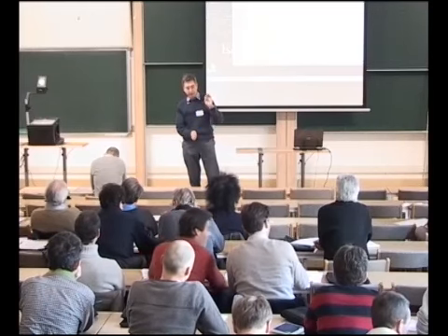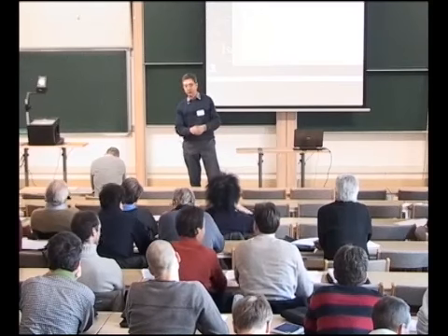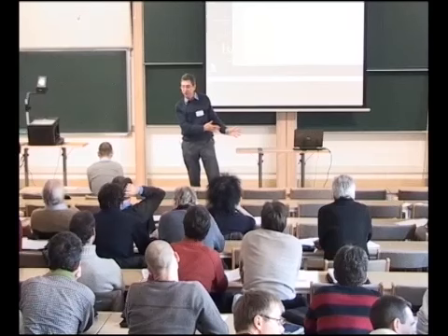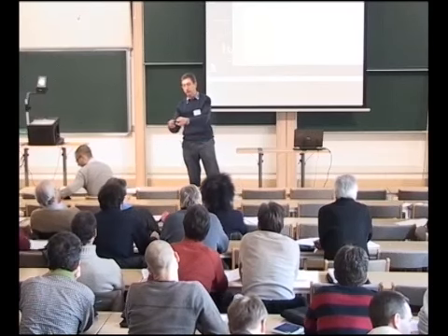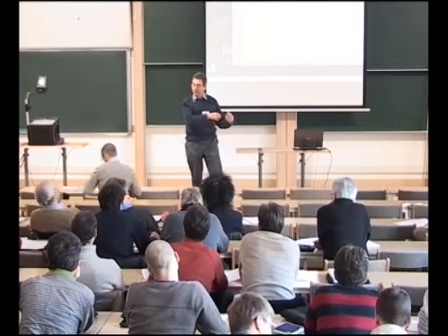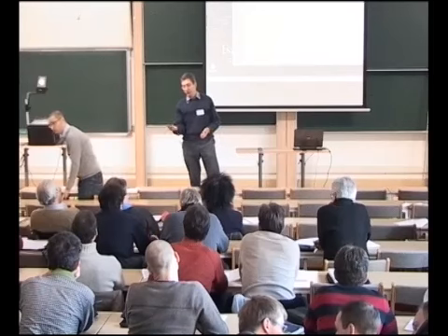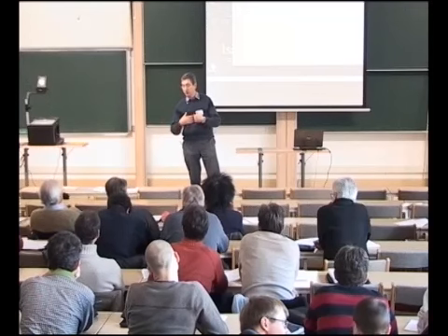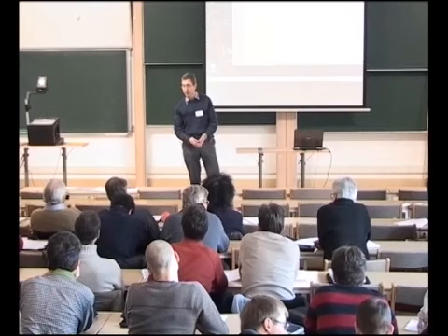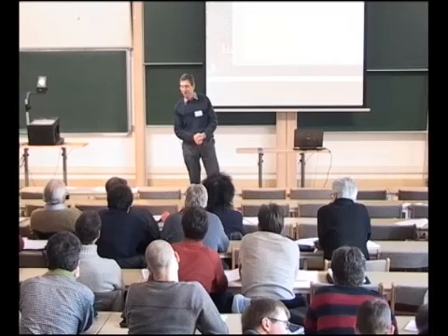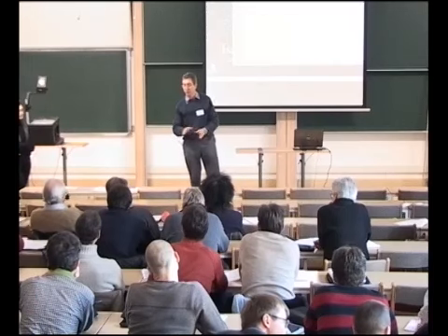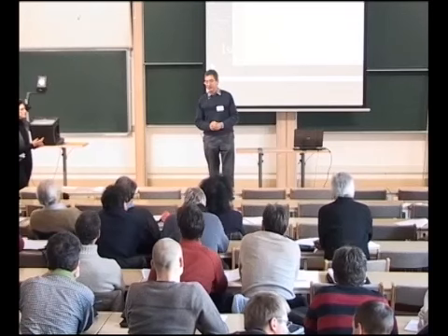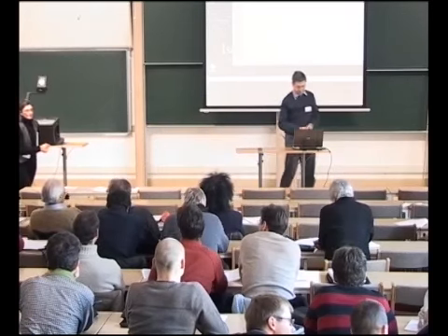I can see that one can't take the limit, as a smaller and smaller RVE, and shrink it to zero. So I can't take that limit. So I can see that there is residual inertia, but I can't actually see residual couple stress. So I call this a reduced Cosserat model. And I make that choice that I will get rid of the couple stress and retain the rotational inertia. I could very easily reverse that if it turns out that I'm wrong. I don't believe it's inconsistent. It seems to me that it does correspond with what I see in granular materials, and I'm just trying it out to see if it works. But if you know that it's inconsistent, then please tell me why.